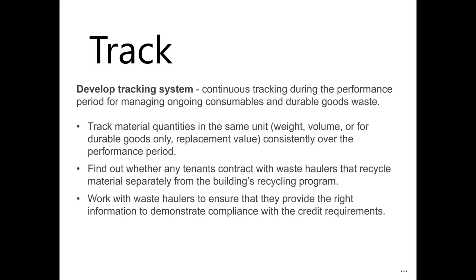Work with waste haulers to ensure that they provide the right information to demonstrate compliance with credit requirements. So you want to speak with your waste vendor early on and say, do you have a sample of recycling reports that you would typically provide so I can take a look at it? And then you want to make sure that once you have that sample report, it's covering the metrics you need. Is it in the unit that you need? Does it have the material breakdown that you need? So on and so forth.